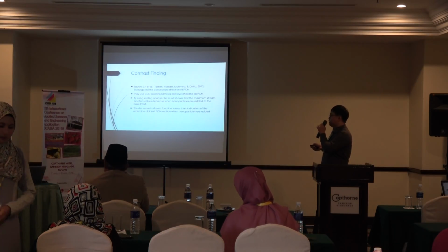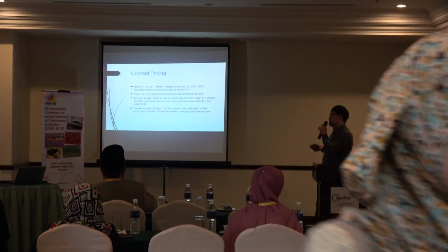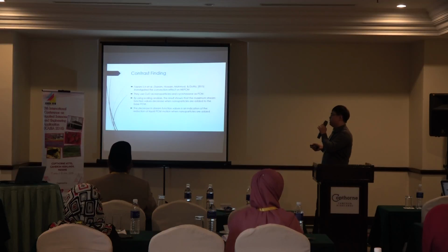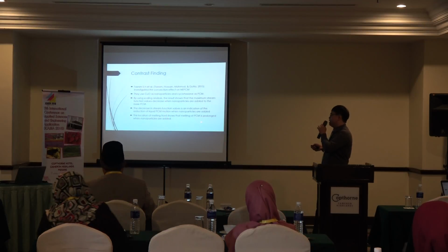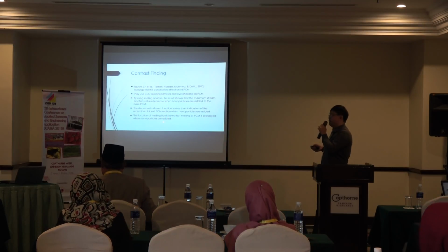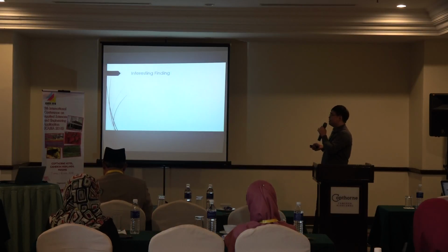The decrease in the stream function values is an indication of the reduction of the liquid PCM motion when the nanoparticles are added. The location of the melting front also shows that the melting of the PCM is prolonged when the nanoparticles are added. But only a few researchers came out with this conclusion.